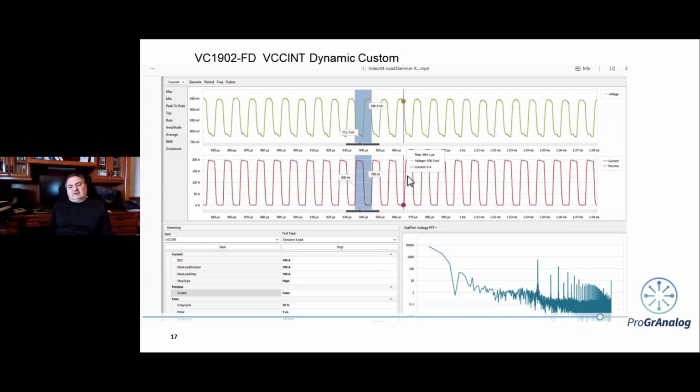This is when we're doing a duty cycle sweep. Remember how you have to capture a lot of repetitive pulses to find a weakness, or the weak point, of a regulator. So this is basically him pausing and zooming in on a capture, whether just to prove that it's okay, or he may have found something of interest.